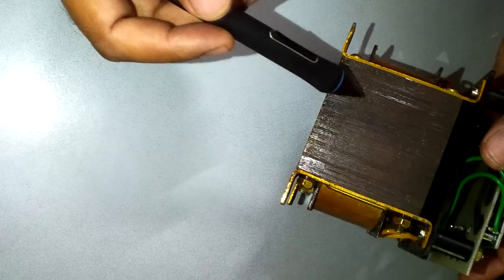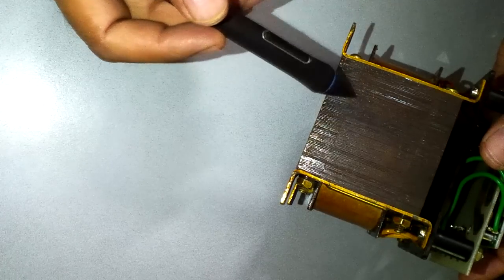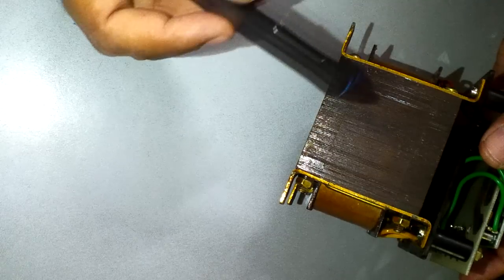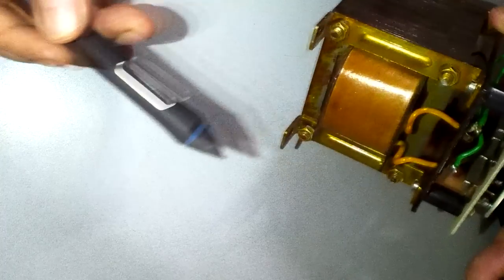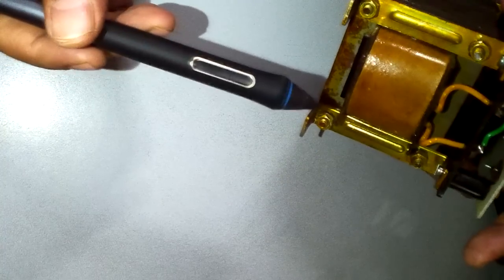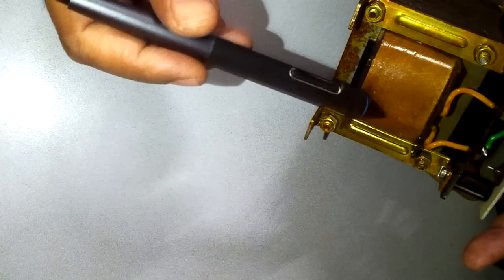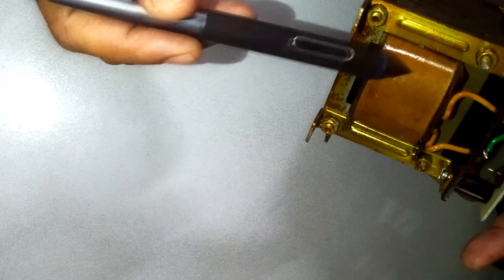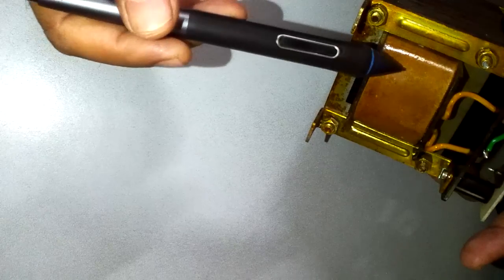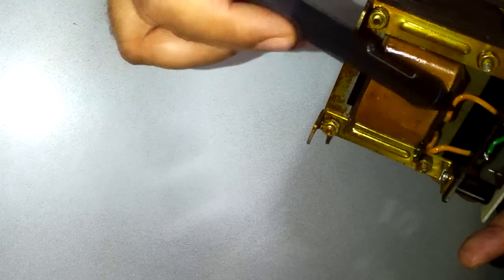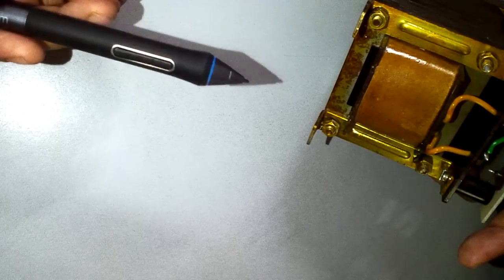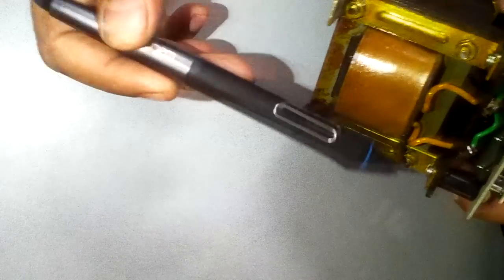So these are the common transformers which you would have seen, but these are for low frequency applications or 50 hertz applications. And if I rotate it over, you could probably see that this is where the winding is housed, and this is a parchment paper, and underneath is the copper winding. Both the primary and the secondary are wound here, and then they come out and then terminated here.